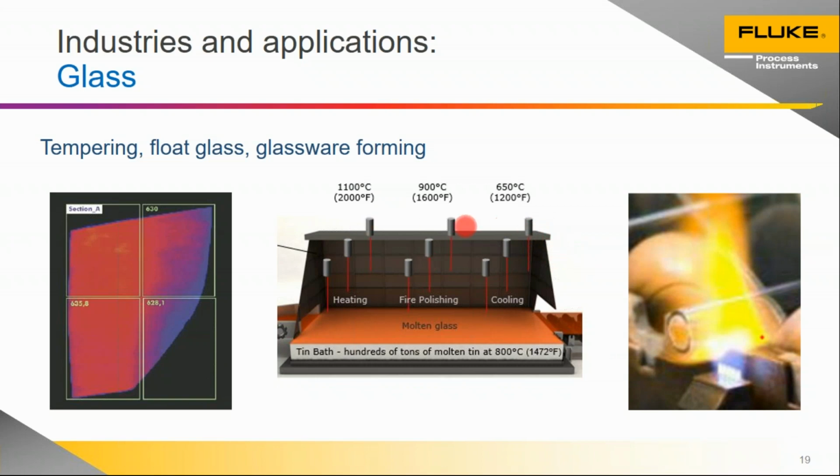Now, in almost all these cases, it's advantageous to use a 5-micron device, whether it's a pyrometer or scanner, so that you're not looking through the glass. You saw that glass is highly transmissive at the lower wavelengths, but if you're up at around 5 microns, you can start seeing the surface of the glass instead. And in some cases with very, very thin glass, there's even another wavelength at 7.9, almost 8 microns, where it's common to use that.